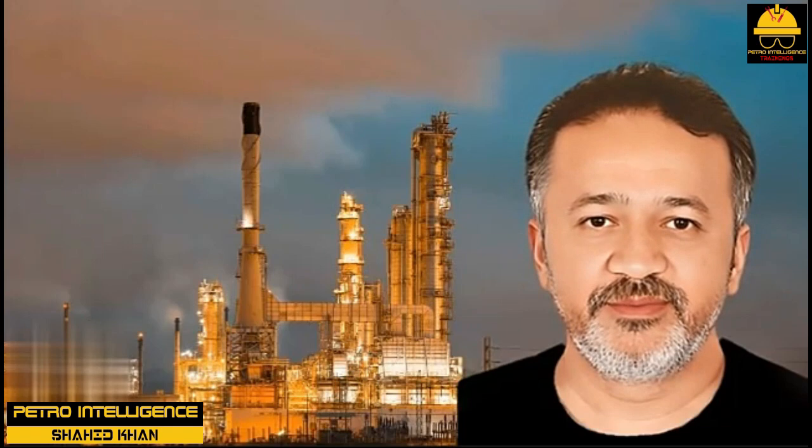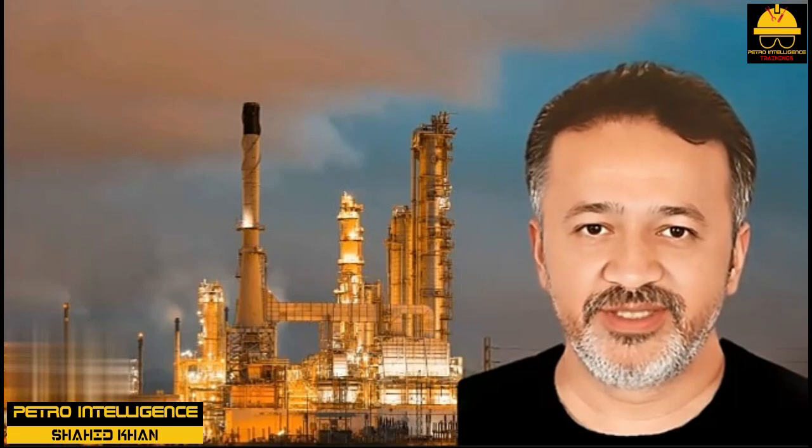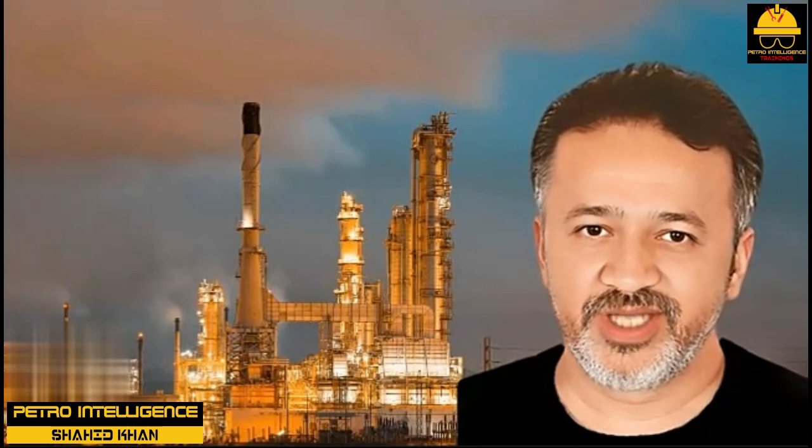Today we will discuss why we control distillation column pressure and what are the options for optimizing tower operating pressure. Why are distillation towers designed with controls that fix the tower pressure? Naturally, we do not want to overpressure the tower and pop open the safety relief valve. Alternatively, if the tower pressure gets too low, we could not condense the reflux. Then the liquid level in the reflux drum would fall and the reflux pump would lose suction and cavitate.